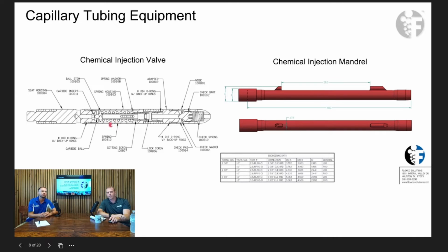And so that pressure regulator, chemical injection valve, is there to essentially artificially hold back fluid in the tubing. That's right. Okay. Which again, we'll talk about the next thing that can help you out too, up at surface. Now, sometimes I see operators just run a check valve instead of the chemical injection valve. You can do that. The issue is that you're taking that risk of just dumping each time. Gotcha. Okay, so you see that more in your CO2, that kind of stuff. Interesting. And so this is more of a controlled pressure regulation of that chemical.